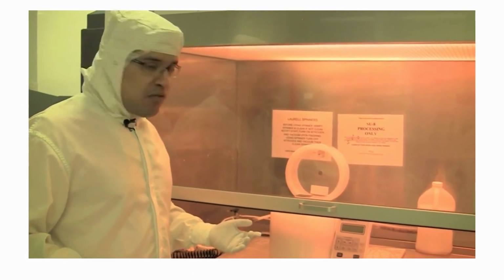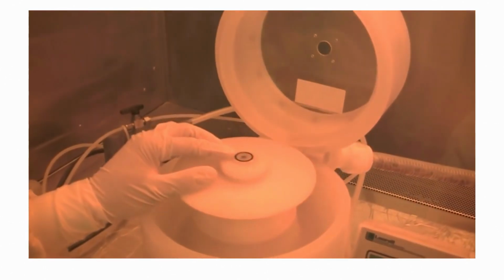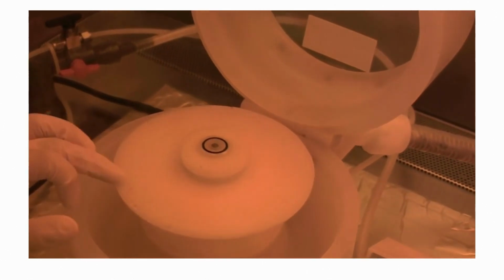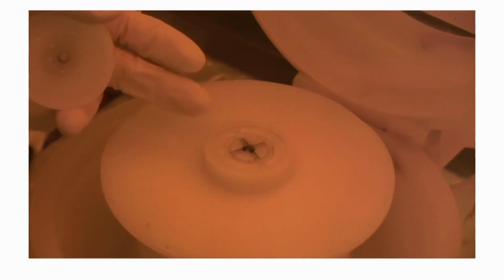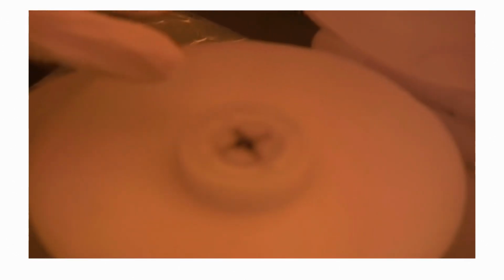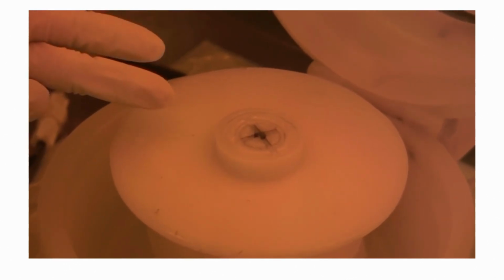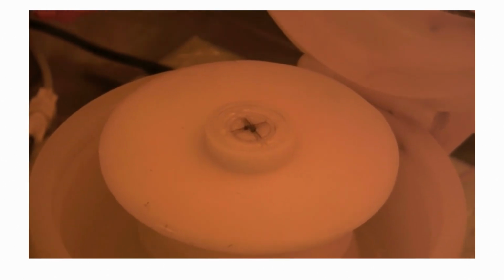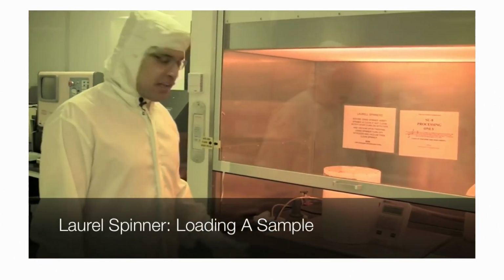Another thing is we don't want photoresist to go inside and clog the valves. On this chuck here is a small hole. Now, when you don't clean the photoresist around the tool, it can actually crawl and get sucked into this hole. As you can see, it's a little dirty in there. You see how the photoresist is in there? Someone didn't follow this direction, so you can see it's dirty. That will eventually get clogged inside. And if it gets clogged, the vacuum line won't work. And if it doesn't work, then you can't spin the photoresist. So it is all very important to follow so that we keep our tool up and running and prevent it from getting damaged.